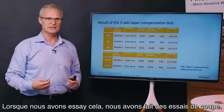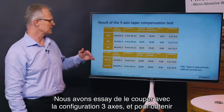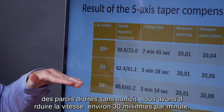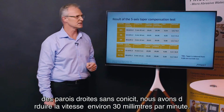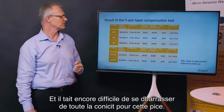When we were trying this, we have been making test cuts. We tried to cut with the 3-axis setup, and to get straight walls with no taper, we had to reduce the speed to approximately 30 millimeters per minute. And it was still difficult to get rid of all of the taper for this part.